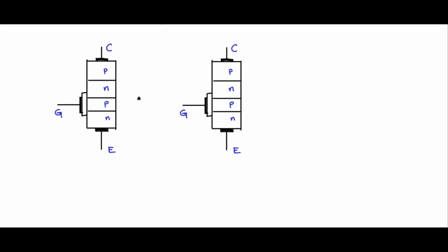So let me duplicate this. The operation is very similar to MOSFETs, and you can understand it in this fashion. Let us make a break in this fashion. Let us split that top N type in this fashion and make the connection like this. So the N type is split. So this top N, PN, this PN is a PN junction. It is like a diode. So we can replace this portion by a diode in the equivalent circuit.